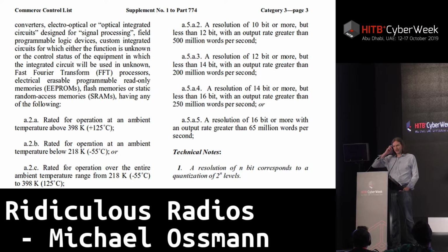So we put some thought into this, and we realized that we should be able to do it, we thought. But the key thing that we needed to realize was that we weren't going to get very good dynamic range. We weren't going to be able to pick up very weak signals. So we needed to make sure that we had some analog circuitry in front of our 1-bit receiver that at the very least did some amplification and hopefully some filtering. And we thought, well, where could we get a circuit that has amplification and filtering and maybe mixing that we could just salvage from somewhere?